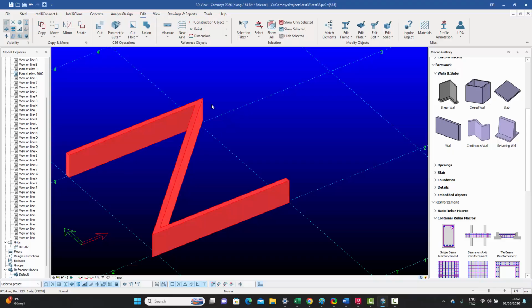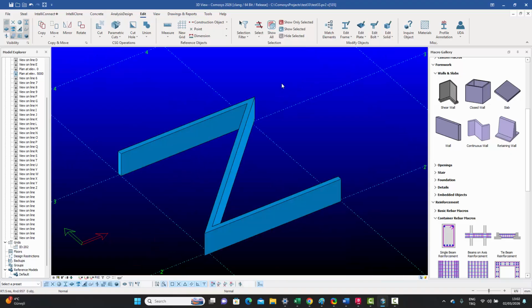You could manually still make them separate objects, but then you will need to do all that end cutting by yourself, and then you will have 3 separate marks. If that's not very important for you, then it's better to do it like this, as a kind of a folded plate, if you will. And you can then double click on this and make changes as well.